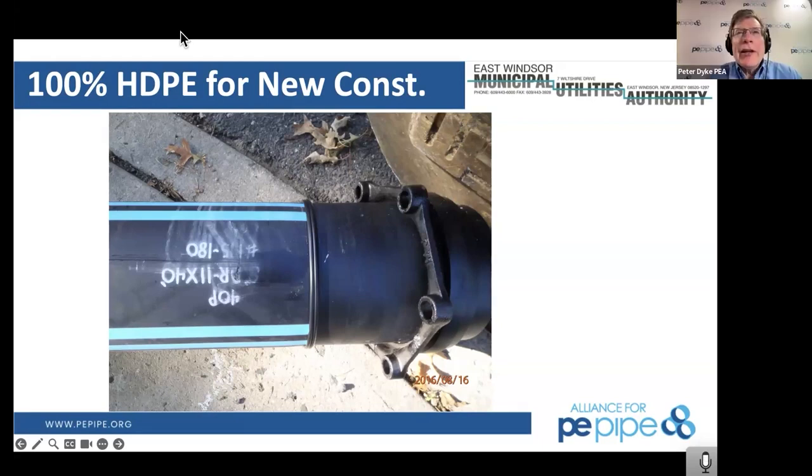Sure. You know, that data logger, Richard, now the new upgrade of it, or the new software, it's kind of like Tesla. They send out these new upgrades. It permits you to do pressure tests. When you do one of those hydro tests, you can hook it into, Dan Landy's got a presentation on this. You hook it into that pipe string, and it reads the pressure, so that you can document the pressure testing on those pipe strings.